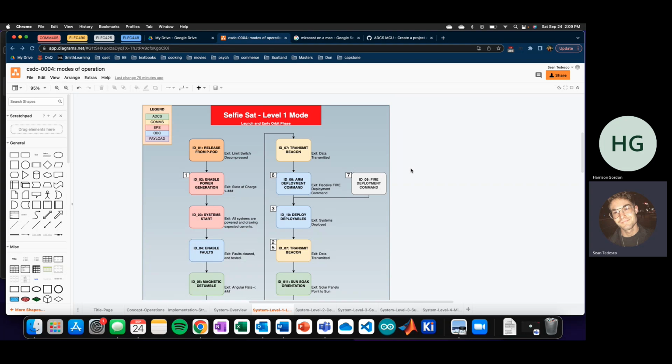Yeah, that's a really good question. The biggest mechanical task that you would need to do is the antenna deployment. And there's a couple things that I would then ask, like, in what areas would that not work? Did the melt or the trip wire not melt, or did an antenna arm break? And so I would then ask, how do you detect if it's melted? How do you detect that it's broken?